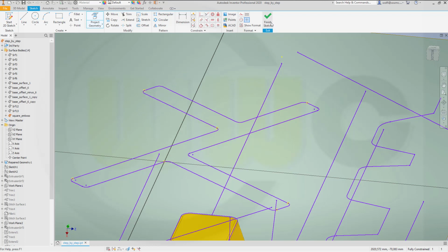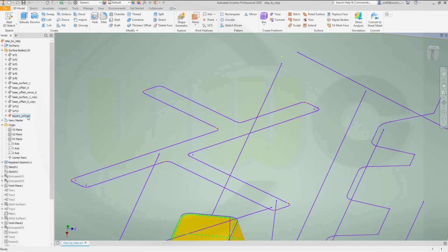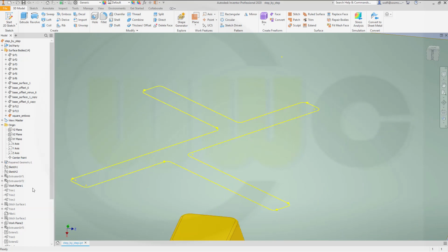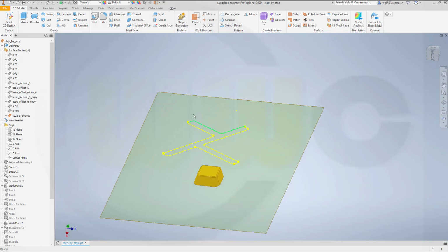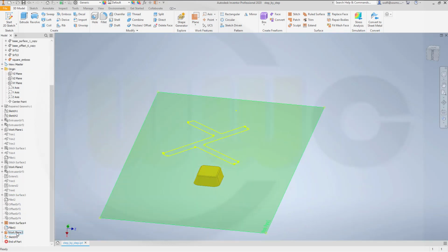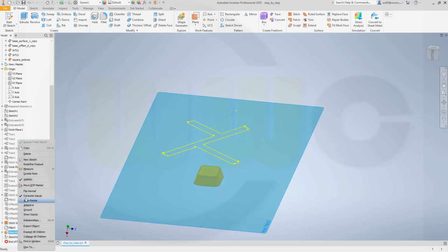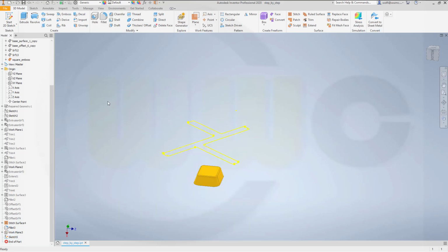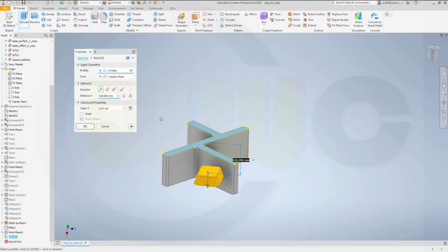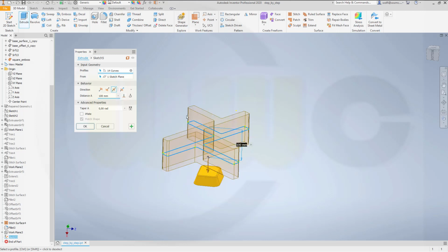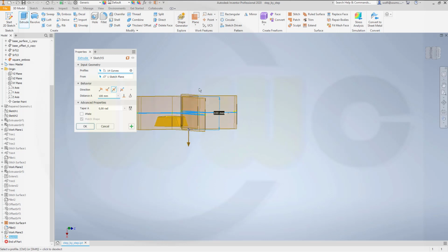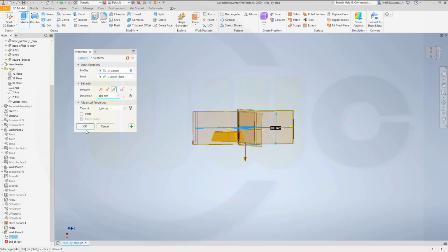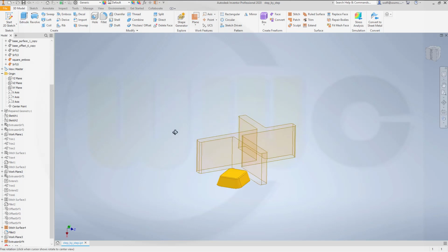so maybe I have all of them. Let's finish that and take a look by hiding these. This looks good. I could hide, of course, the plane. Okay, let's make an extrude. Make it a surface. Make it symmetric, make it 100, might do. Should be okay. And confirm.